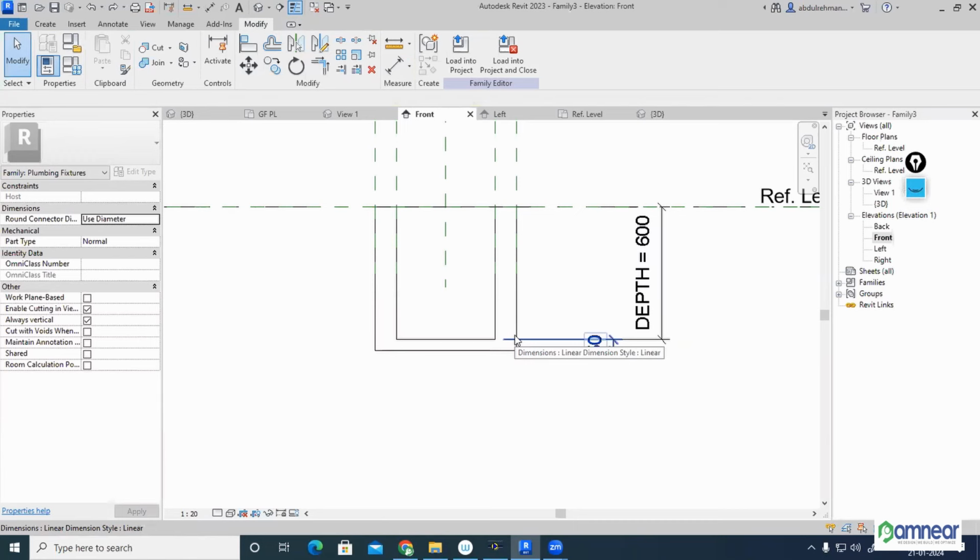Okay. Now I should connect my inlet. See, inlet diameter, as I told, 4 inch, schedule 40. A small spigot, like what you can say, like a collar, same like a duct collar, or a spigot, you have to show where the pipe has to be connected. So I'll be slightly projecting a 50 mm projection from here. There, my pipe end should come. When I'm making, you will be getting a clear understanding.